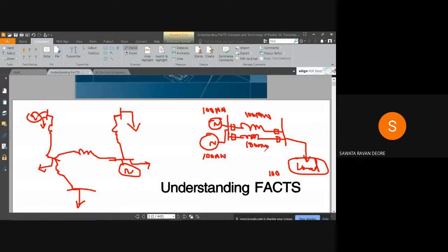So, in order to improve the reliability of this isolated power system, for each and every component of the power system, we need to have an alternative. For the source, we need the same rated alternative source, which we call reserve capacity. We need to build the transmission capacity at double the load capacity, in parallel, since a single line will not be sufficient, in order to handle the contingency of transmission line outage.